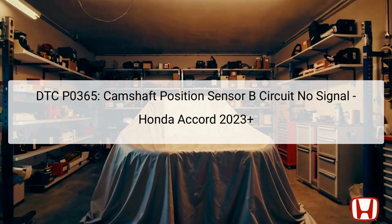The Powertrain Control Module, PCM, located in the engine bay, relies on this input to ensure efficient engine performance. When the PCM does not detect a pulse signal from CMP sensor B, it identifies an abnormality and stores the DTC for further diagnosis.